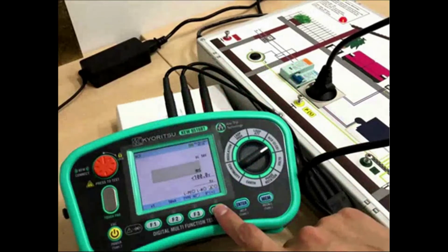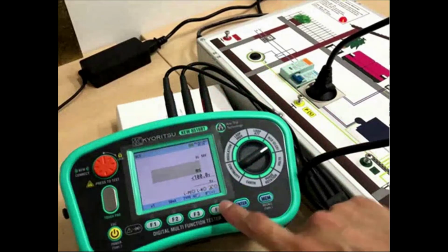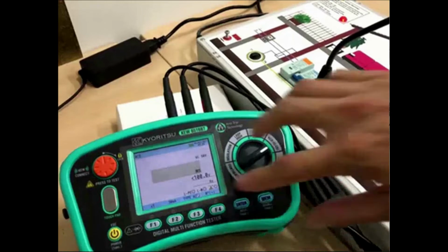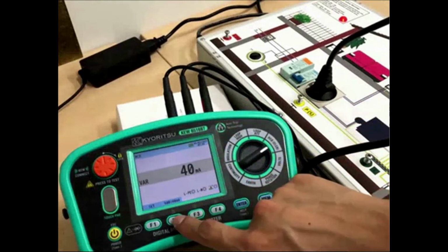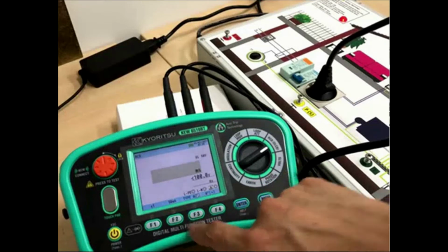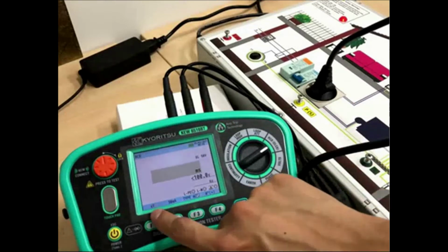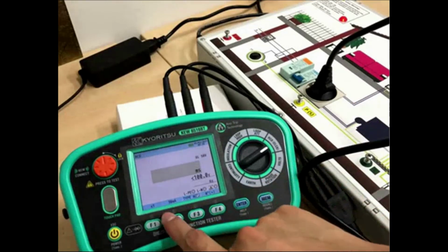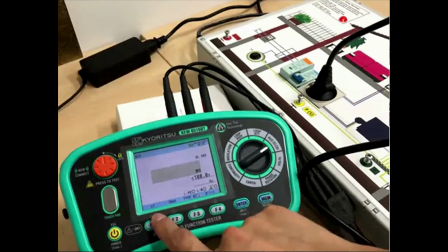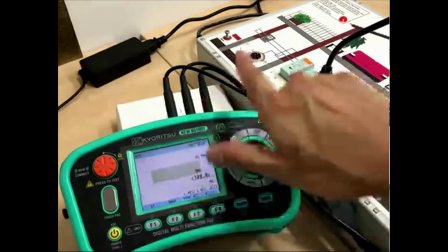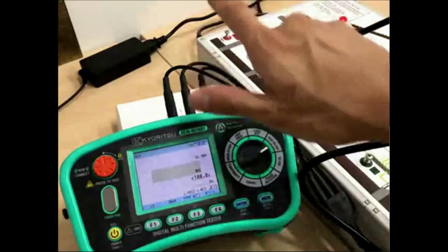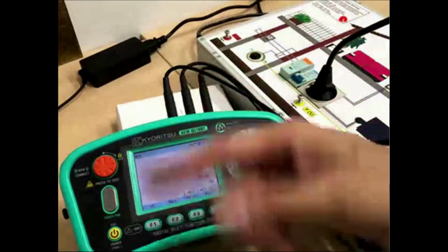Then this is the phase, 0 phase, 180 phase. Okay, understand? So our current is 30 milliamp. Just now I show you already. 30 milliamp. And then this one is what? One time 30 milliamp. This one is the output current from the instrument to test the RCD tripping time, to test how fast it trips.